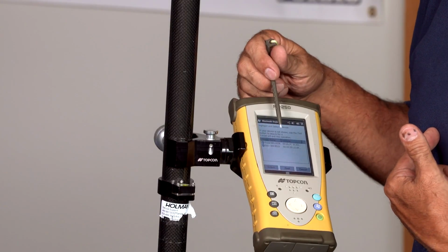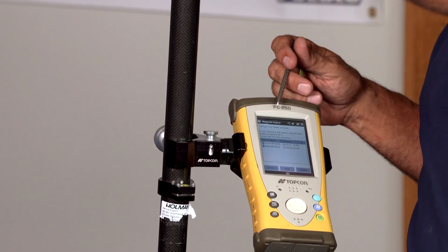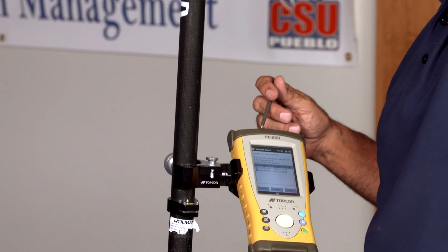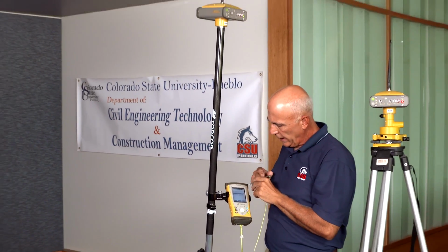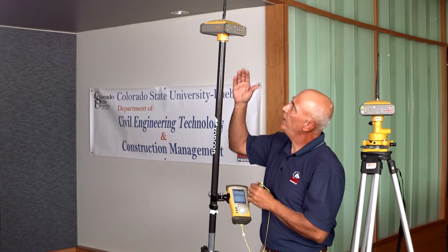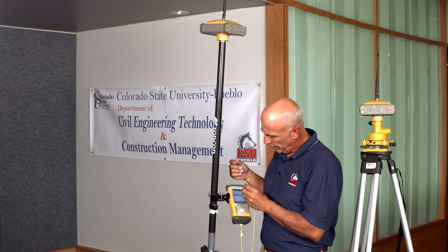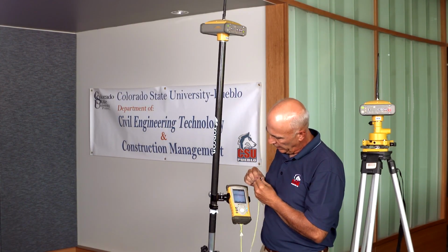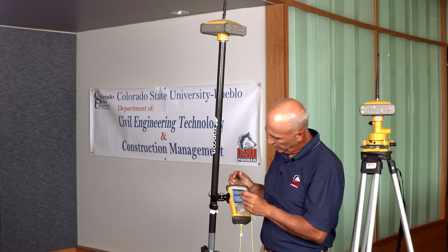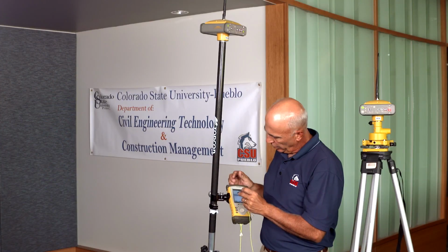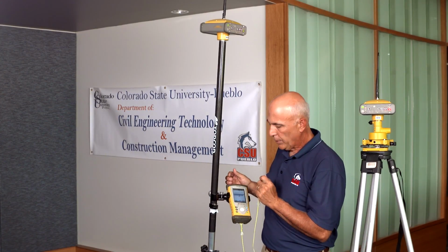Normally the rover unit indicators are given in the serial number, and that's what's broadcast out as the signal. So if I can find the serial number that communicates with the point on the data collector, I would then be able to accept the roving unit. I would select the roving unit and wait for communication.